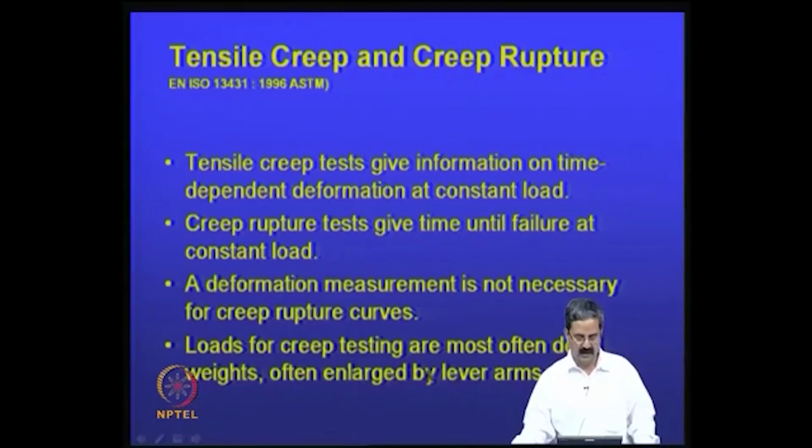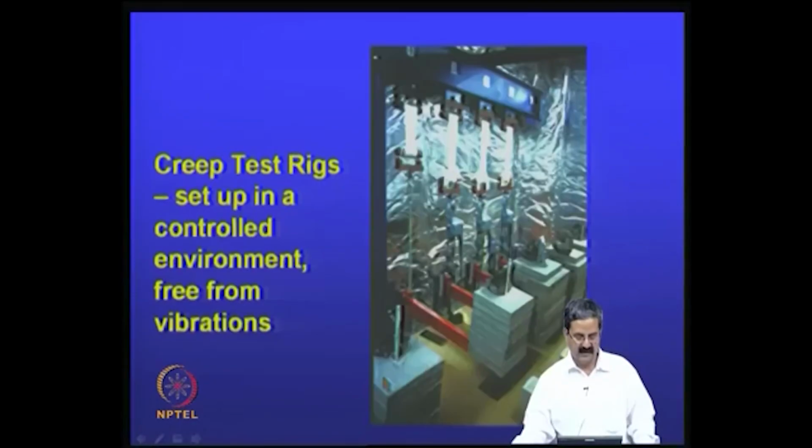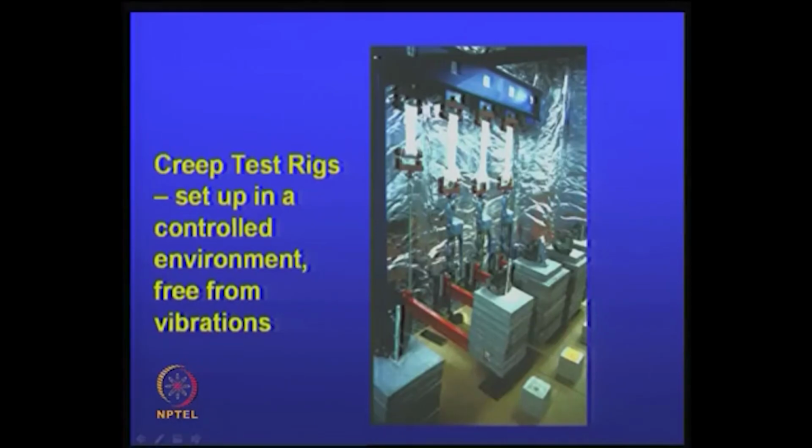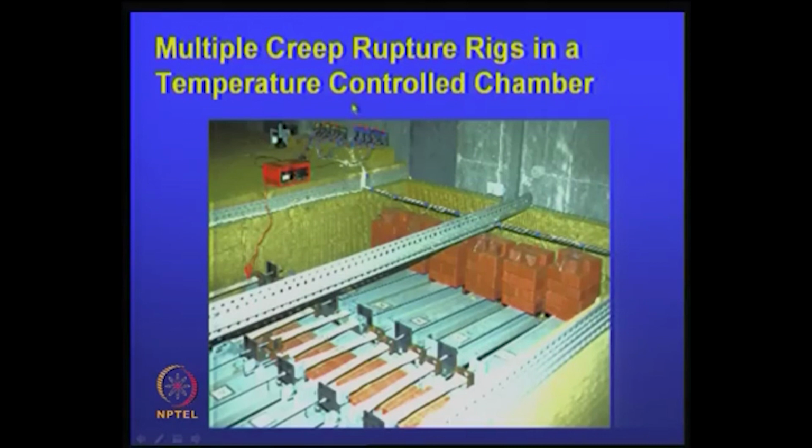So, that needs to be calculated. We use constant loads. Say you have a geotextile piece here, like 1, 2, 3, 4 pieces, with a constant load applied, or a lever arm application can be there, and multiple creep rupture tests in a temperature controlled chamber. In fact, it is a chamber where multiple material tests are being done, this is one.